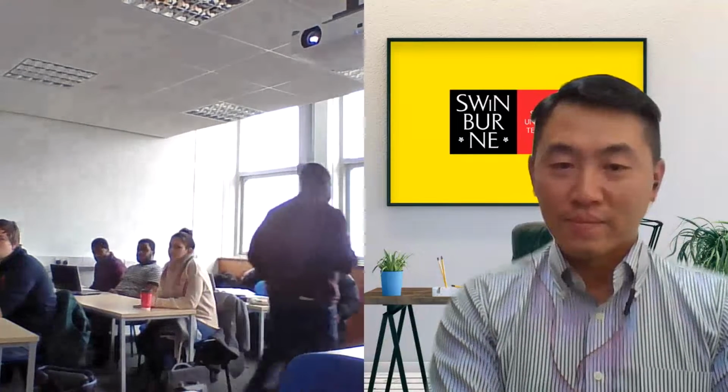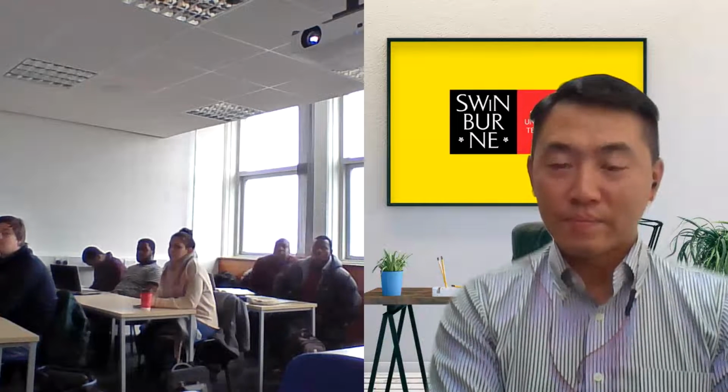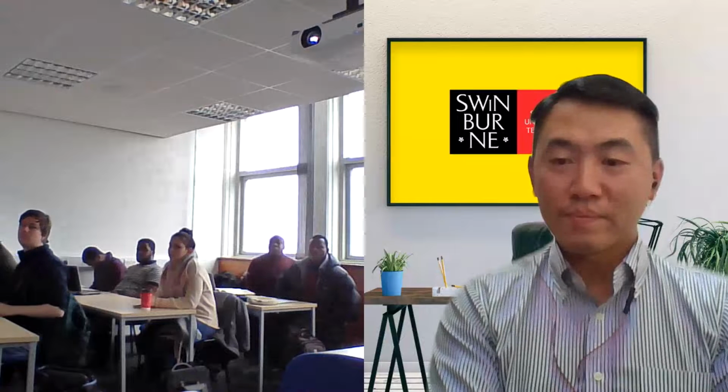That's a good question, Hinjo, because what we observed also was the fact that if there is a difference in size between the different particles, for example sand and the rubber, when they get together there might be segregation. So some of the smaller particles will go to the bottom, and it might not work in the best functional way or how it's been established. So what you're saying is right. You need to bind it somehow, and there are different ways of doing it.